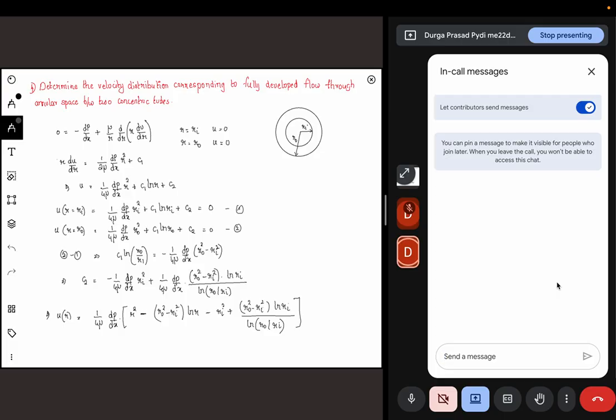Now we can also have a different case which is quite similar, the Taylor fluid flow. What happens is you can make one of these rotate inside another one. This is the kind of scenario which happens in journal bearings, where the outer one will be fixed, and this will be a shaft, and inside you fill this with some lubricant. This shaft will rotate, and because of this rotation you'll have some forces which we will not discuss. But what you are required to find is, let's assume that this moves with a constant omega, determine the velocity distribution that you are going to have here.